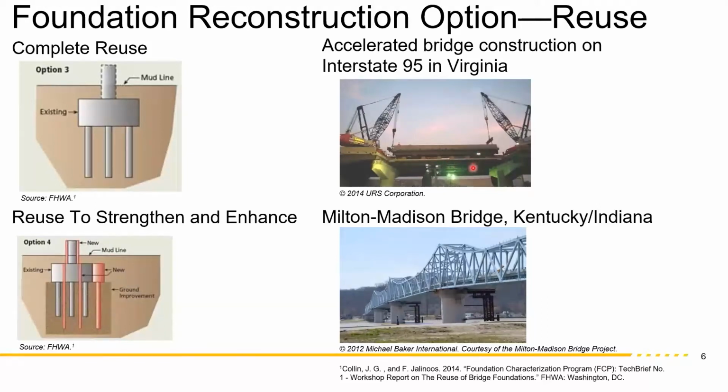$60 million, quite substantive. Here, down at the bottom, they enhanced the foundation by basically putting in a new rebar cage around the existing pneumatic caisson, and they widened the 4 piers on the river. And again here, they prefabricated the steel truss. They brought it by barges. They created these temporary piers. They put it on the piers and slid it 50 feet into place.